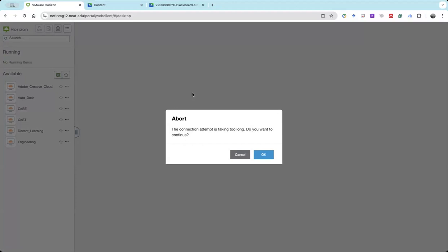Okay, where is it? Under structure foundation and wall foundation. WF1 is under structure foundation, wall foundation. So highlight this one, WF1, right click it, and you will see hide unselected.